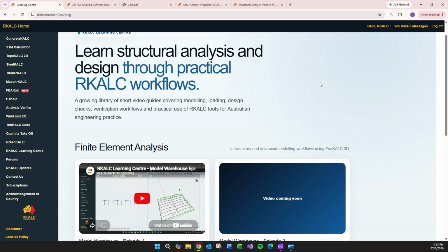In the previous episode, we modeled the main structural elements, the geometry, dividing the frames, applying supports, and we ran a sanity check, just one analysis to see if the moments, shears, and reactions are making sense. In this episode, we'll be assigning the sections to all of the frame elements, applying the loads, gravity and wind loads, and reading the results. We will also verify the results.